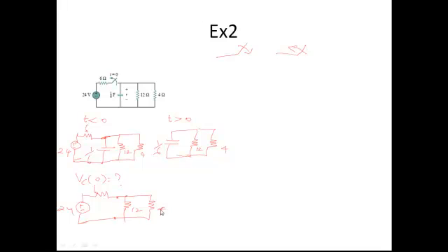So you have to find the voltage across this point. What you can do is simplify this network. The 12 and 4 ohms are in parallel, and this combination will give you 3 ohms. So I will write the voltage across the 3 ohm resistance here.